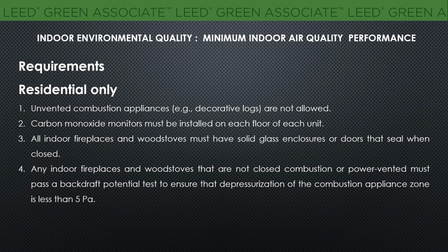For residential only projects, there are some other criteria other than this carbon dioxide concentration and opening requirements. So let's look at that. Number 1, unvented combustion appliances, for example decorative logs, are not allowed. Then along with the carbon dioxide monitor, a carbon monoxide monitor also must be installed on each floor of each unit. All indoor fireplaces and wood stoves must have a solid glass enclosure or door that seals when closed.